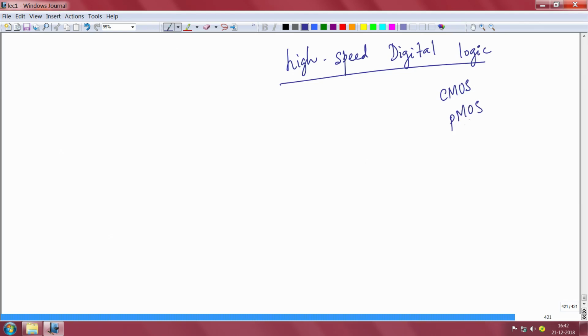Okay. So let us come to the whiteboard and finish up what is pending of transistor applications. The last application that I said we should discuss is high speed digital logic, and frankly speaking, it is something for which all the MOSFETs that we have talked about in this course are used. So essentially we are talking about CMOS. CMOS stands for complementary MOSFET. So you have a PMOS and an NMOS, which means you have a P channel MOSFET and an N channel MOSFET, and you can use them to make inverter sort of things, right.